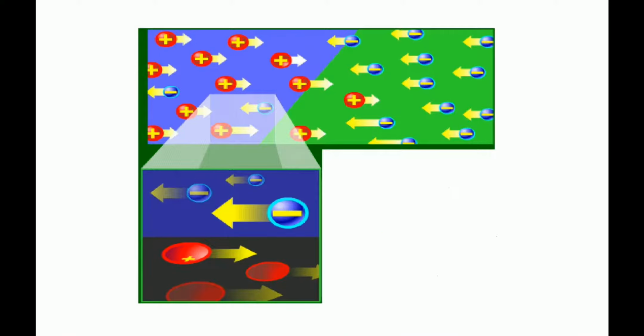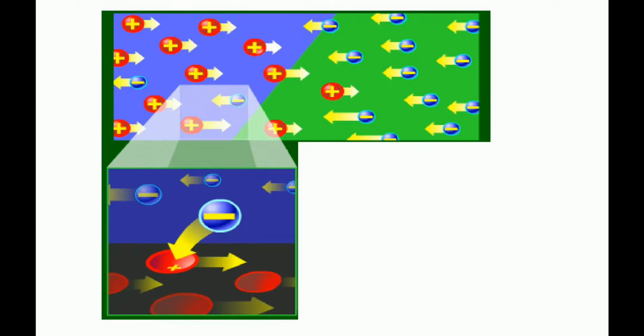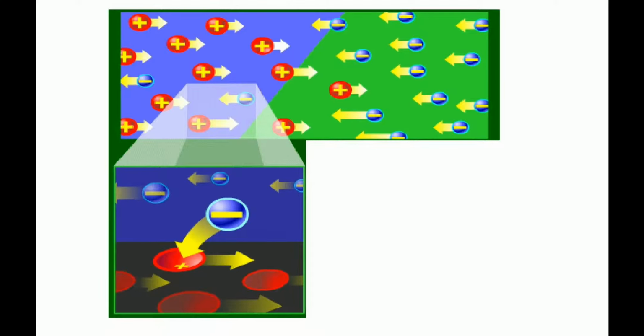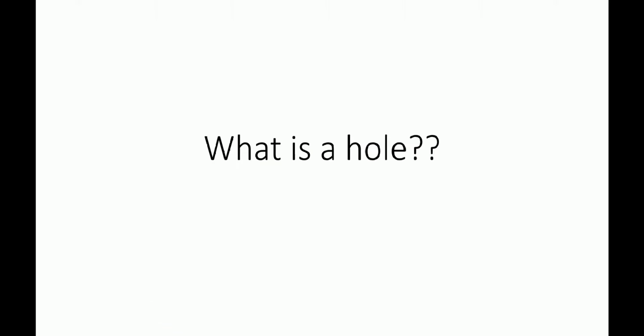When current flows across a diode, negative electrons move one way and positive holes move the other way. The holes exist at a lower energy level than the free electrons. Therefore, when a free electron falls, it loses energy. This energy is emitted in a form of a photon, which causes light. The color of the light is determined by the fall of the electron and hence energy level of the photon.